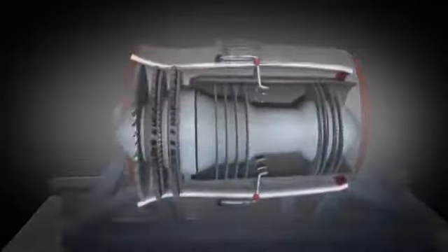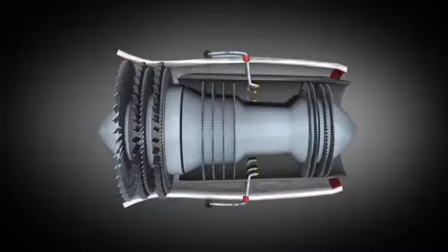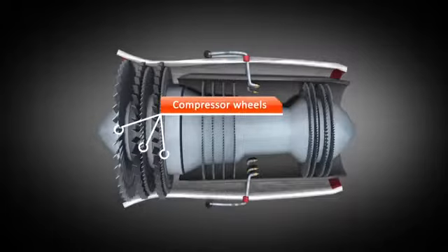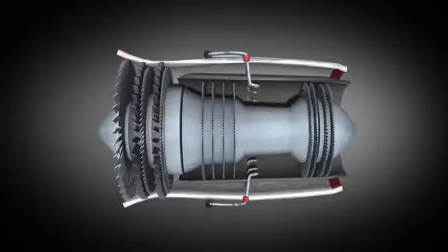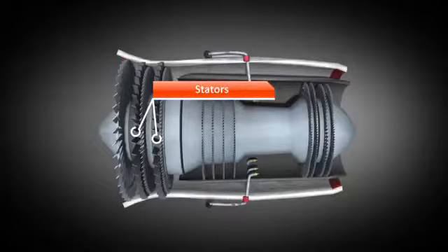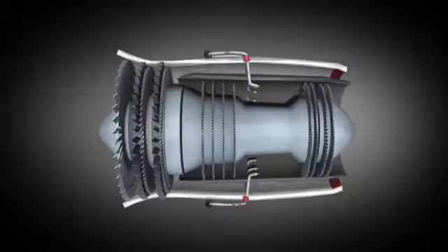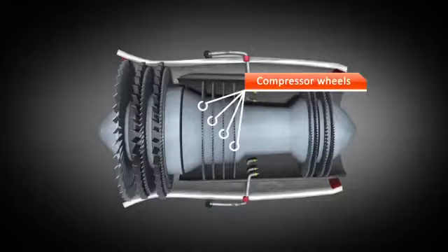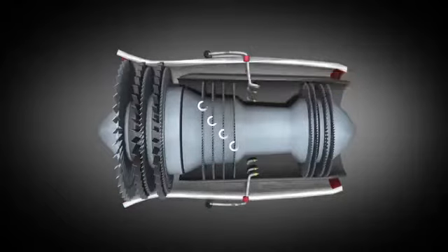Today, we mostly use turbofans, also referred to as fan jets. In the front part of the turbofan, which is shown here, are 3 rotating compressor wheels, which are often called the fan. Not only do they suck in a great amount of air, but they also start compressing the air sucked in. Stators are installed between them, which are firmly attached to the nacelle. Only 2 stators are represented here, but usually there is a stator after each rotor. This is also the case for the other compressors, which are installed in the core of the engine.